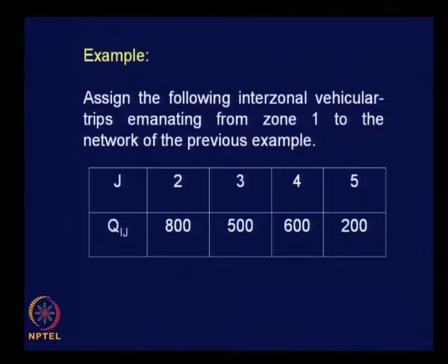Normally traffic volume is quantified in terms of PCU, passenger car unit. You may recall we discussed the conversion of person trips into vehicular trips, that is one stage. Under the highly heterogeneous traffic conditions prevailing in our country, we cannot just measure vehicular traffic in terms of number of vehicles, even though it may be approximately okay under highly homogeneous traffic conditions where around 90% of vehicles are cars.